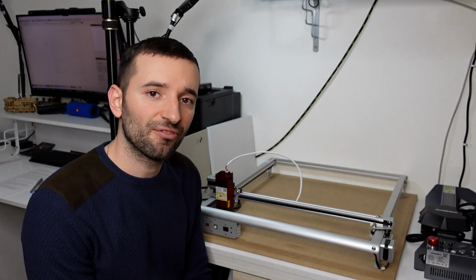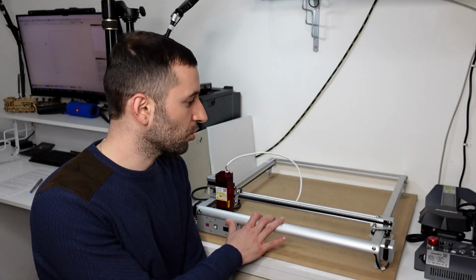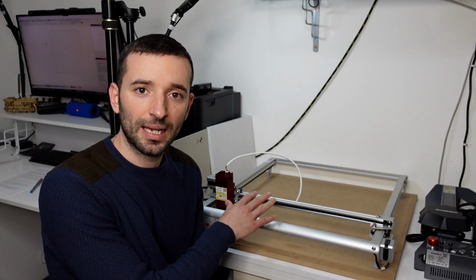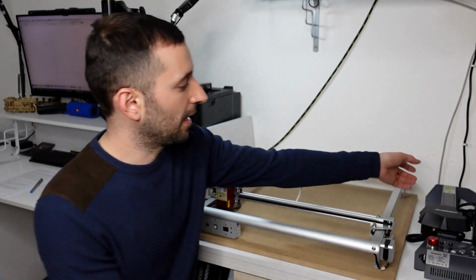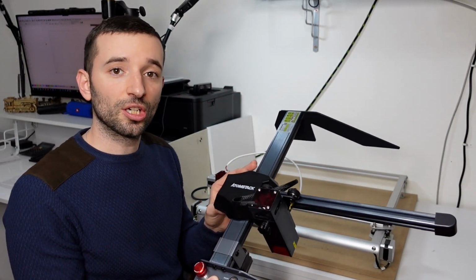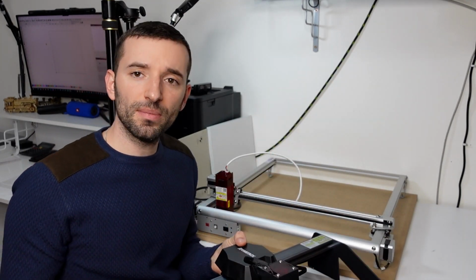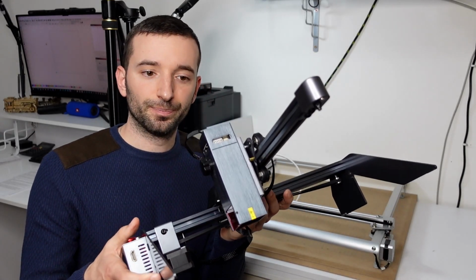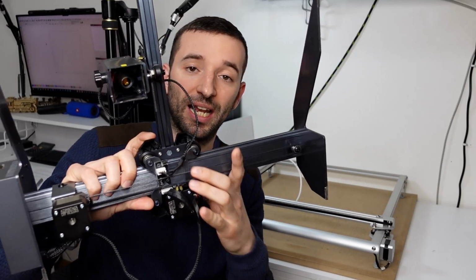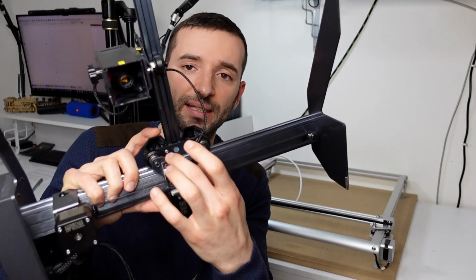Before getting any further, let me introduce you to the concept of home. The machine that I'm showing you right now is without home, or we could shorten that and say homeless. This machine instead is a machine with a home. What is the home? The home is basically a set of sensors or simple micro switches, which are electromechanical devices that sense movement.